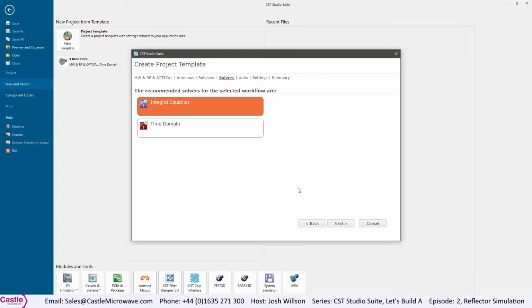Since the integral equation solver is based on non-local operators, every element couples to all other elements. This leads to a linear equation system with a dense system matrix. There are different approaches to solve the resulting memory and time problems. The equation system can be solved directly by the direct solver for small and medium problems. The dense matrix can be approximated by ACA for electrically small or medium problems. Both solvers are available in special accuracy integral equation solver parameters.